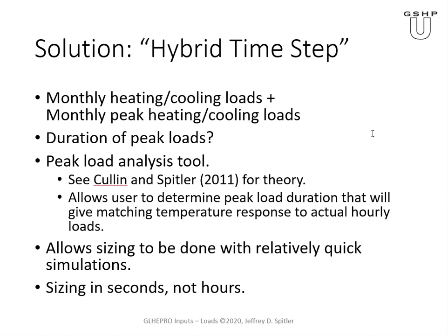And the way we do this is we use what's called a peak load analysis tool. And I think I mentioned in the last part that this is a spreadsheet. It was originally intended to be incorporated in GLHEPRO, but that hasn't yet happened. The theory of this is discussed in this paper by Cullin and Spitler. And what it does is it allows the user to determine the duration that will give the matching temperature response to the actual hourly loads.